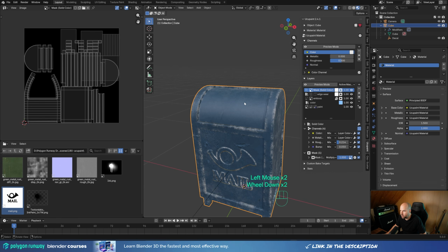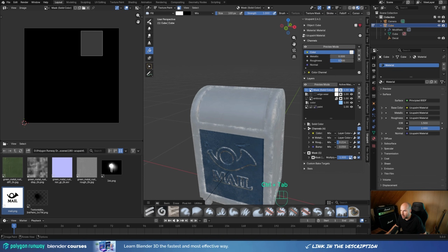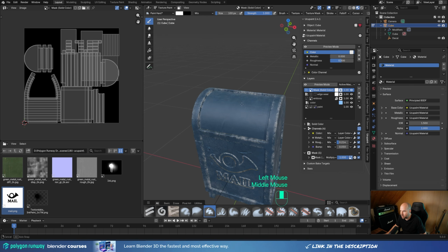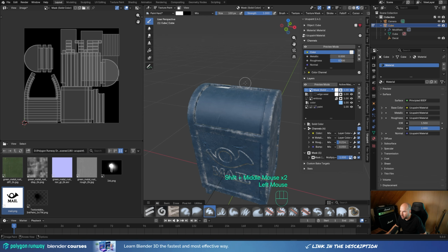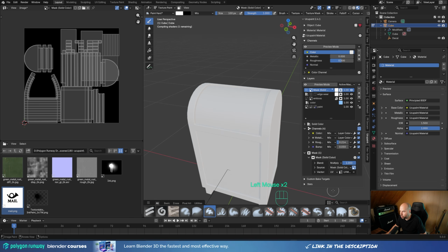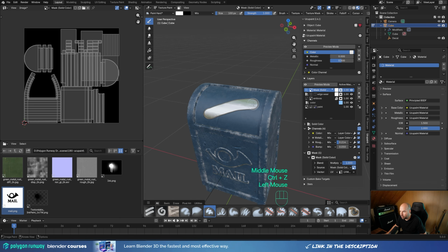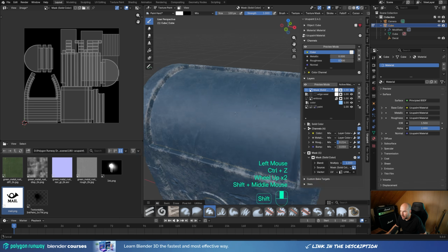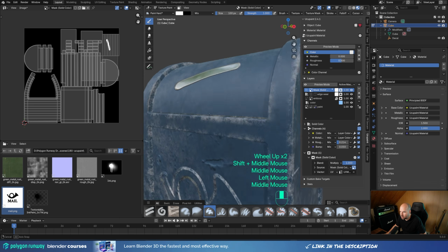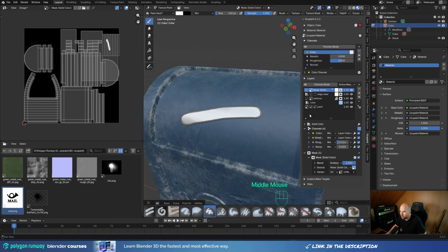You can see it in the UV editor, and if I go into the texture paint again and choose brush, and let's disable this paint mask so we can paint everywhere. But if I try to paint here, this is not behaving, because in the mask you have to set the vector to UV. And now you can place your brush strokes, and just like this you can create the brush stroke and put all of that information that we set up on that piece of your model.